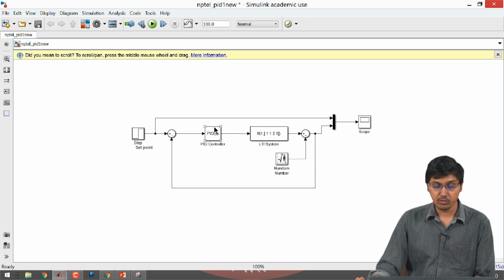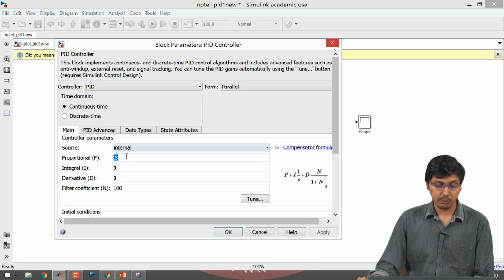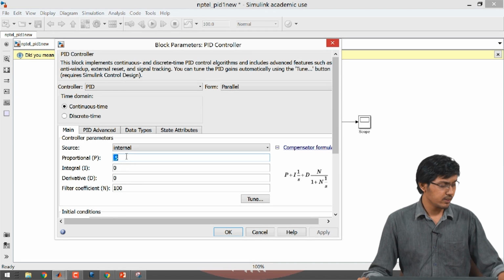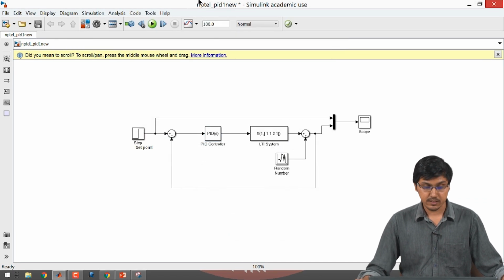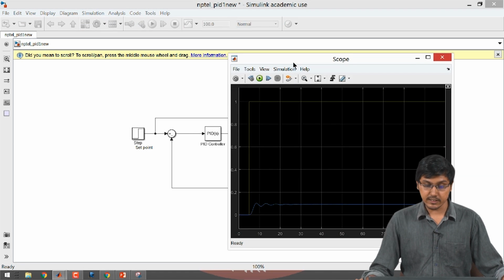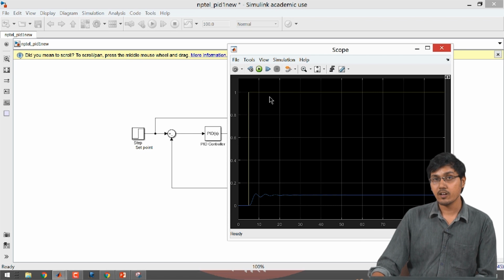Now, just remember the value of proportional gain Kp we have. Let us start with a small value, so 0.1, and Ki value is 0 and Kd value is 0 again. So, we are just going to see how the system behaves. Now, if you look here, the yellow line shows the set point change, this is how we wanted the output of the process to vary, but what has happened is the output has changed from 0, it has increased, but it has some error.